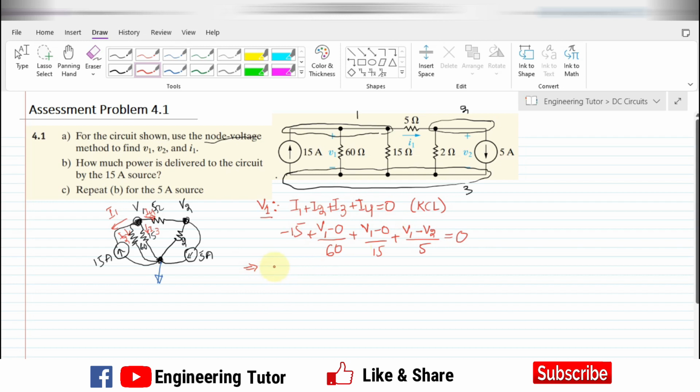So when I move it to the other side, by simplifying the equations, I will have V1 by 60 plus V1 by 15 plus V1 minus V2 divided by 5. This is equal to 15. Okay, so now for solving this equation, we have to take the LCM of the three terms, which are 60, 15 and 5, and the LCM of these is basically equal to 60.